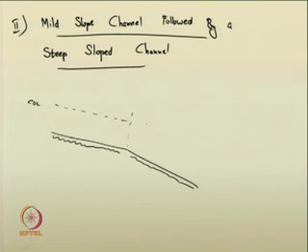You can again go and recall the module 1 portions. So, the critical depth line here, the critical depth in both channel 2 and channel 1 are same, but this is a mild slope channel having S01 and this is a steep slope channel, bed slope is S02.